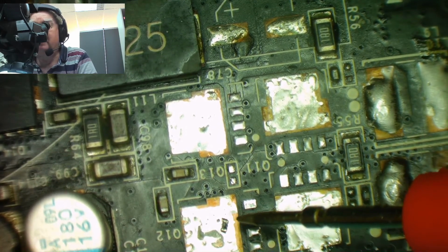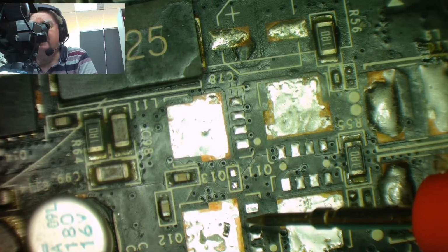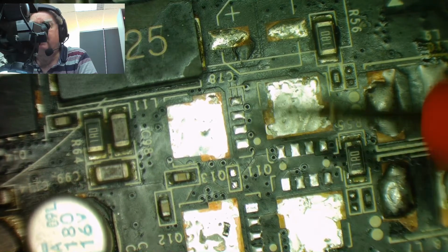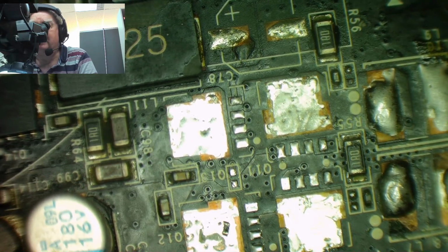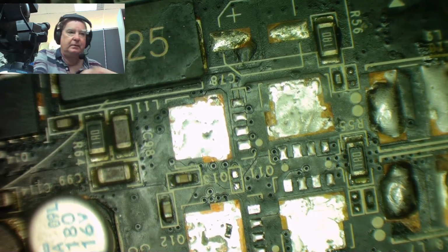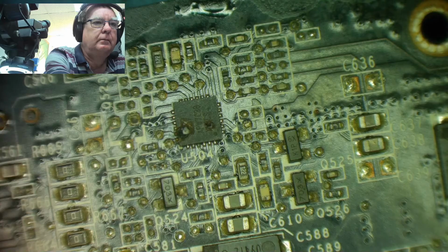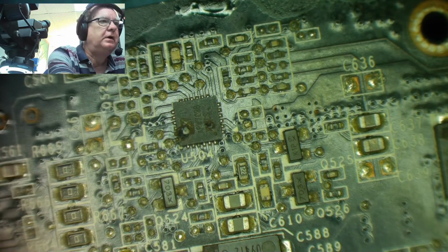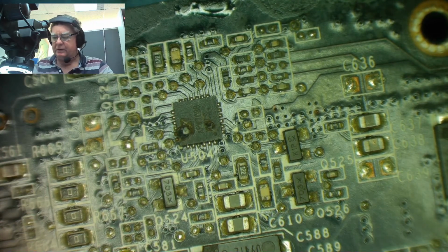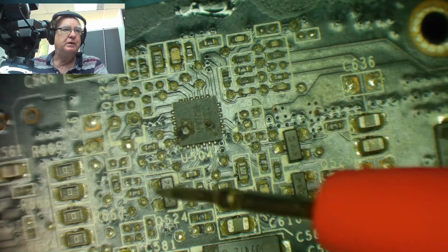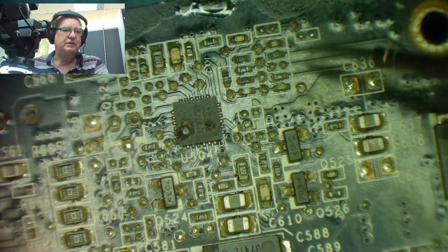That's the idea. So I'll get the data sheet up because we've got a good idea which pin it's going to go to, and let's have a look to see if we can find the other resistor and what it actually is. Okay, so we can see here is the controller chip, the one with the hole in it. Basically we know that the gates of the MOSFETs will go to this chip. It looks like they go via a resistor because I can see one on the other side.